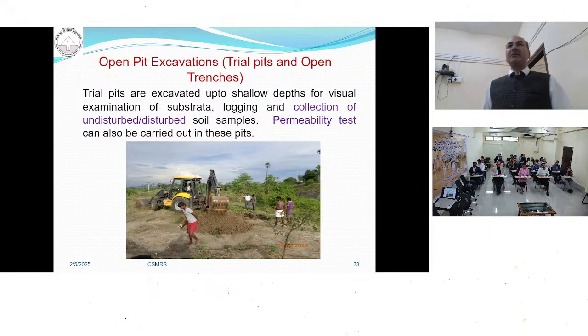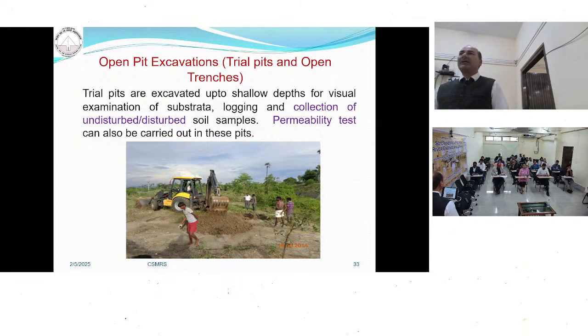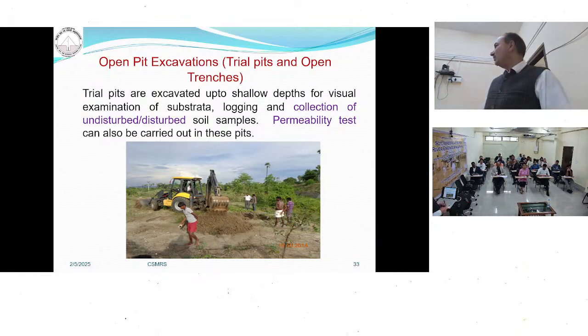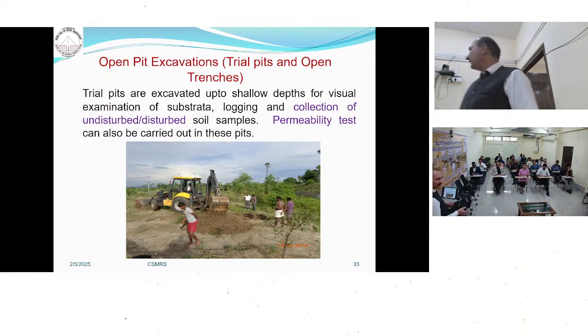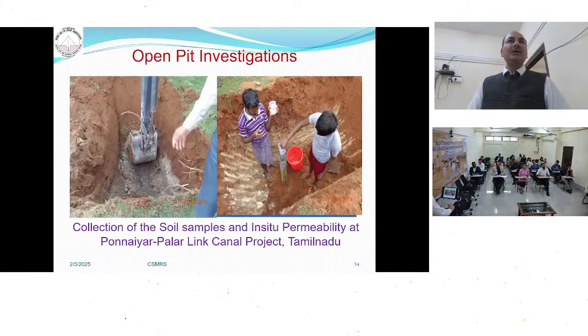So this is a picture of open pit excavation. This was carried out for an interlinking canal project. The canal was around 60 km in length. So for that, what will you do? Except where it is crossing the bridges or other structures, in normal ways, you have to carry out the investigation up to 4 to 5 meters. That is more than sufficient. So we make the pits